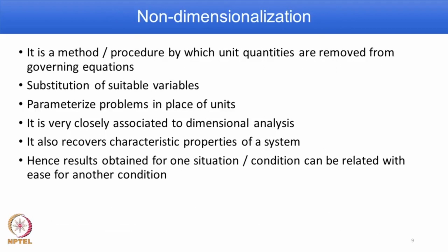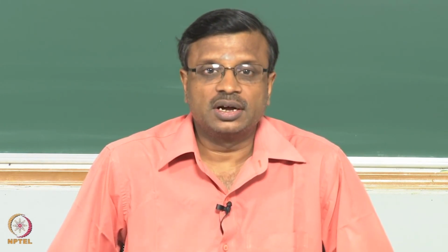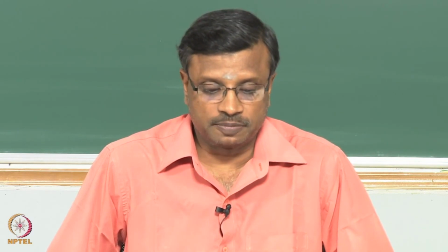Next important topic is non-dimensionalization. What is the meaning of non-dimensionalization? It is a method or a procedure by which unit quantities are replaced. So, we have seen three major equations: mass, momentum and energy. In all three equations we have also observed there are variables: velocity, density, gravity, viscosity, then temperature. All these variables have units. So, is there a way by which you can remove the units and solve the equations in non-dimensional form? And there is a procedure, known as the non-dimensionalization procedure.